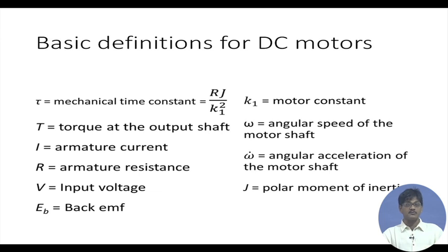But if x motor and y motor are working together, and if their response times are not the same, that means the time required to achieve a particular fraction of the recommended speed, of the final speed, if those response times are not the same, we are going to have some deviation from the programmed path in the beginning, and that means we will have some profile error.